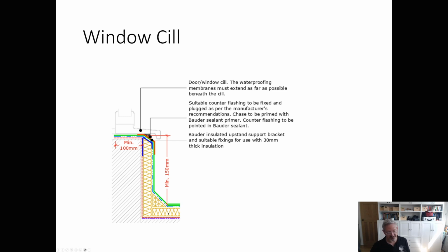I am going to put some insulation on the flat roof, but only a small amount because it's only a workspace, it's not a living space, and I do want to stop condensation, so I want to keep the temperature in there reasonably warm. I'll probably be keeping it warm with heated blankets maybe over the motorbike or something like that, something that just generates a very small amount of heat. And we've got a little bit of insulation on the roof and on the doors and on the floor, so that we can keep that relatively cheaply. We can keep the temperature above the dew point.